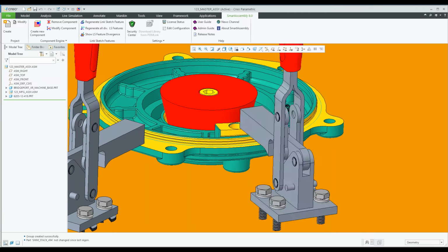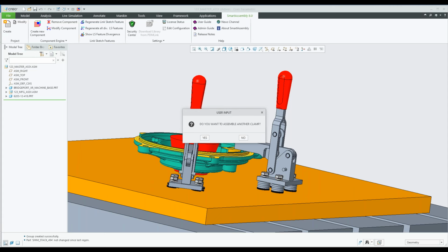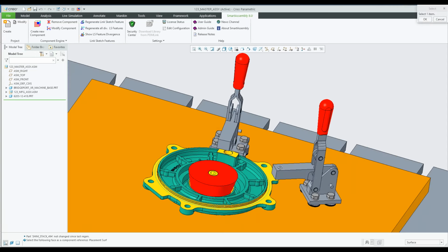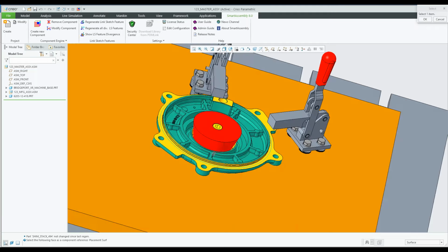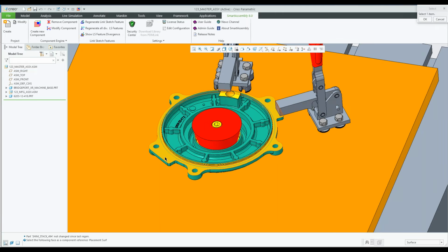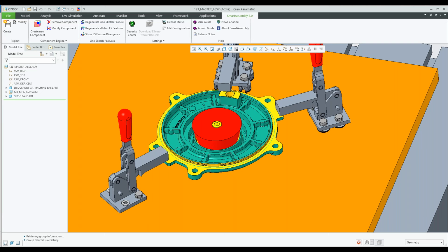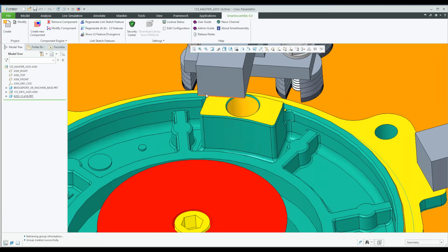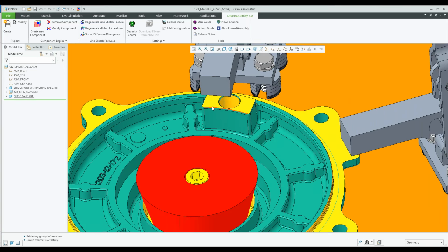Notice that I have a few more washers in here, or spaces. Let's clamp one on this side. I think if we grab it over here, we should be able to hold this down and machine the inside of this or certain sections. Maybe that pick wasn't that great. It should have been more to the center. That's okay. The toolpath will jump over that.